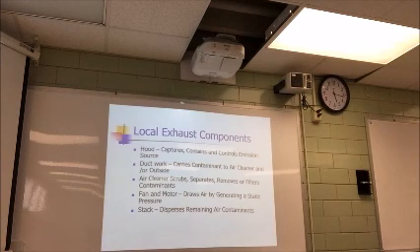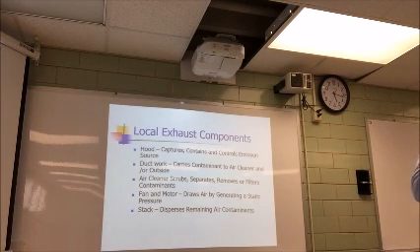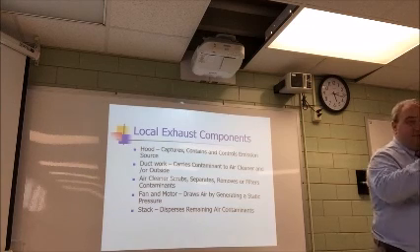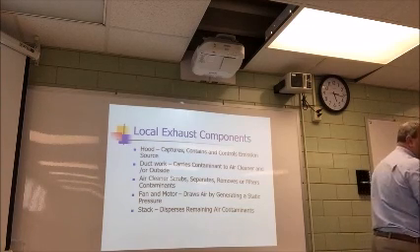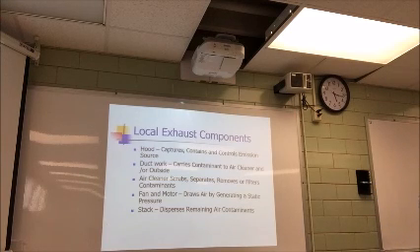You'll hear the term LEV versus dilution. Now, I want you guys to understand, most of the time, you will use local exhaust ventilation, LEV. However, there are cases, and I've been in them, where we don't care. If it's relatively non-toxic, and we don't care that we spread it out in a room, guess what? You can use that. And there's examples.